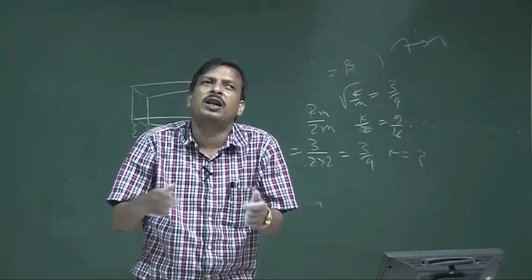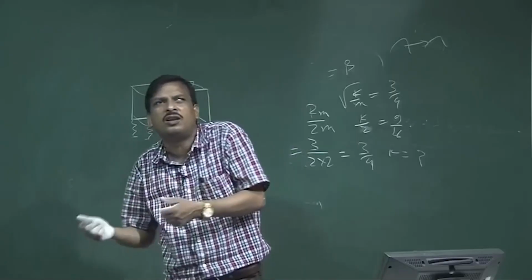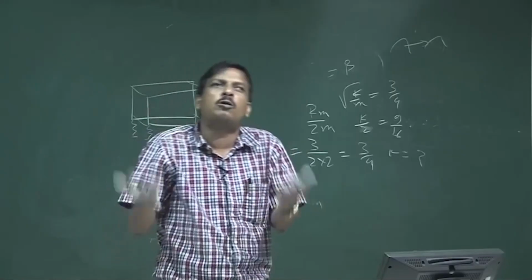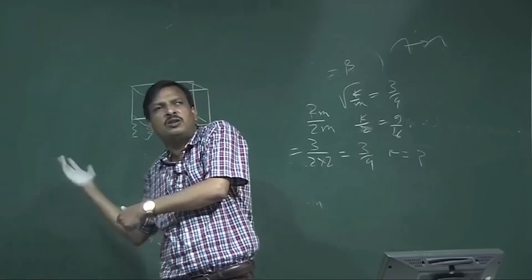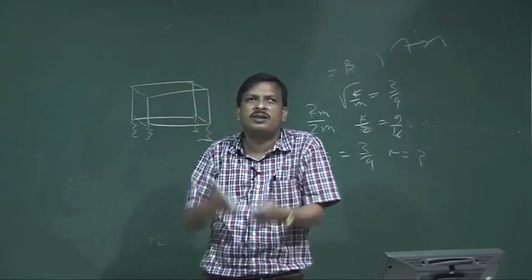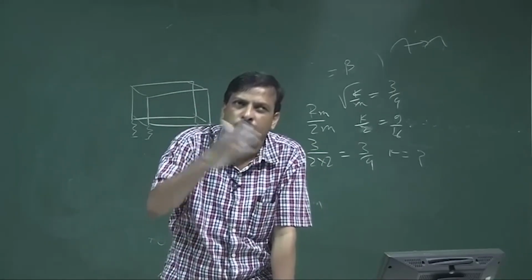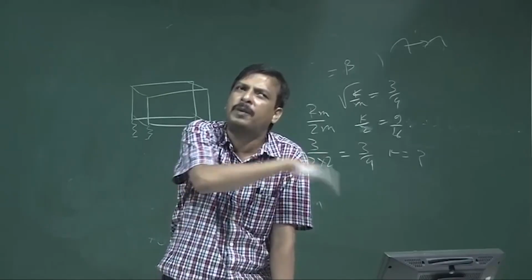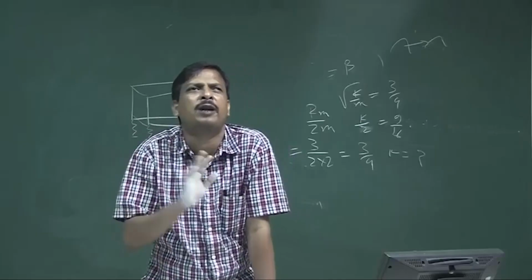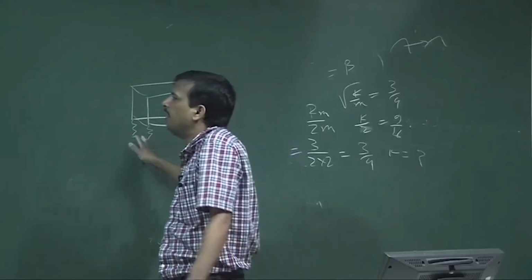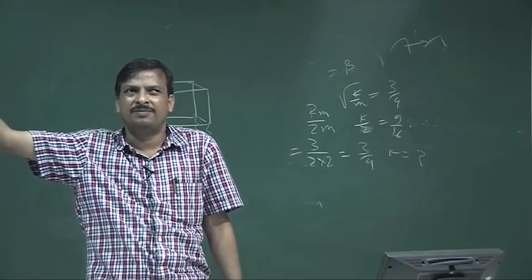If I know the vibration frequency, once my chiller plant is on, force will be applied, and if that force frequency resonates with your system frequency, then what will happen? The chiller plant cannot be stable. So I have to operate the chiller plant below the resonance frequency, or if I know the maximum applied force frequency, then my resonance frequency should be well above this.